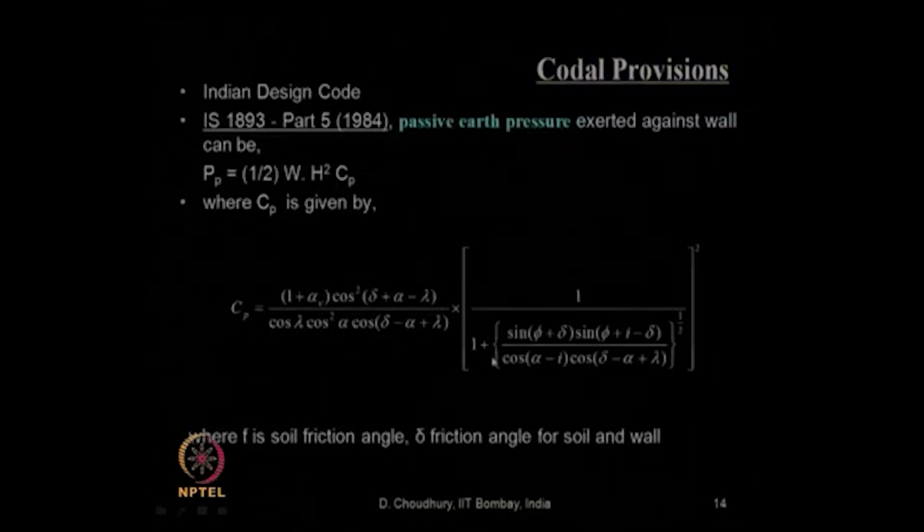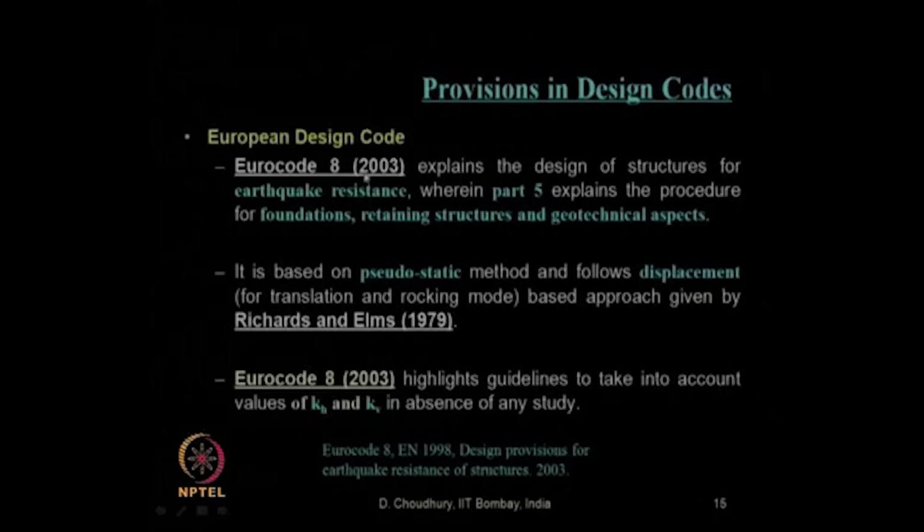Similarly, for seismic passive earth pressure coefficient using the pseudostatic approach as proposed by Mononobe-Okabe, the same formula is given in the IS code also. Whereas, we have seen that the European design code, Eurocode 8 of 2003 version, discusses more about the displacement based criteria. Though the analysis proposed is the pseudostatic approach, they considered the performance based design criteria or the displacement criteria in terms of translational as well as rocking mode as given by Richard and